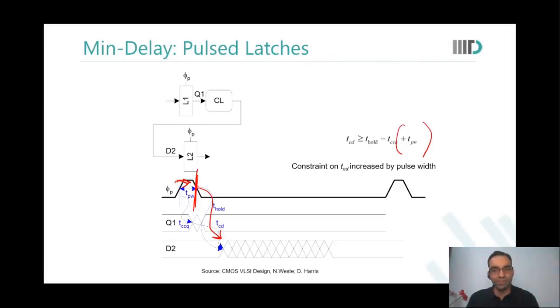Sir, if you try to decrease the pulse width to get a better hold requirement, in that case you will be sending very, very small spikes of clock. Yes, that's a bigger challenge. What is the smallest clock pulse that you can send? That depends upon the setup as well. As I decrease the pulse width, setup will also be pushed back and back. See, as I reduce the pulse width, the system will become more and more like a flop.